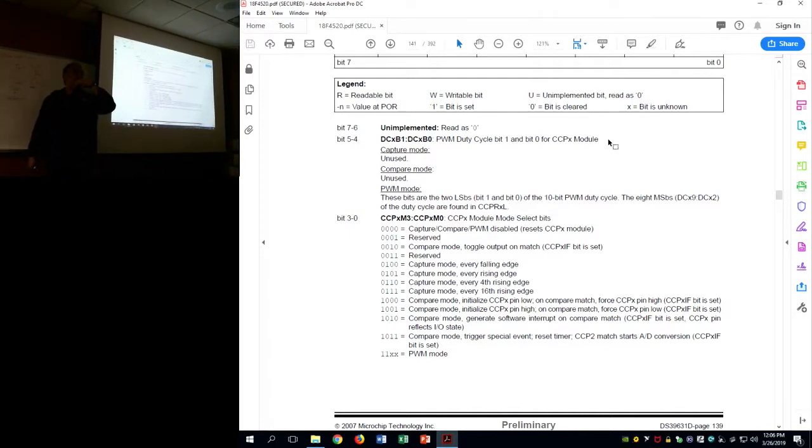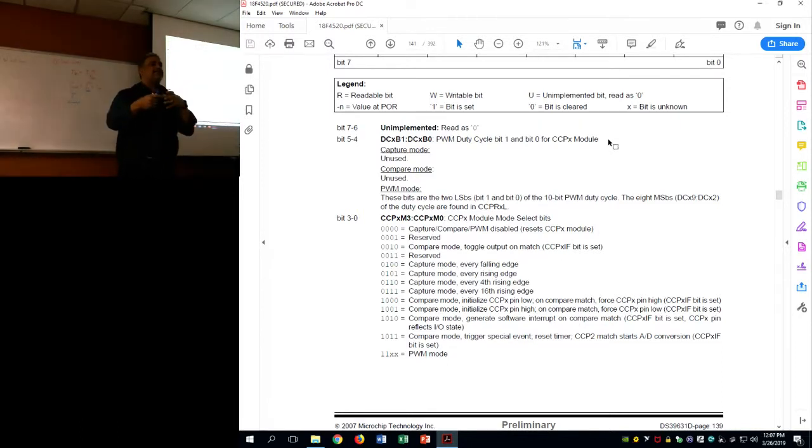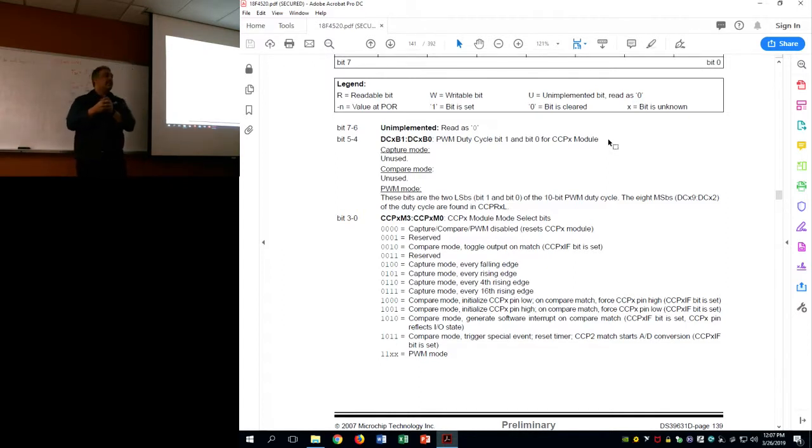Just to give you a little bit of an idea, we use compare mode a lot to generate signals that look like PWM, but have variable power. So instead of having power equal to 5 volts, if you want to vary your power from 0 to 5, 0 to 3, and then change the frequencies and the duty cycle, these compare modes are what we tend to use. We created a pretty cool application where we take medicine that goes into a chamber, and then we create plasma inside of the chamber to change the chemical composition of that gas, and then deliver that gas to the lungs of children in the intensive care unit. We were using 4 of these timers operating together to create variable amplitude and variable frequency across a specific amount of time. So this is a very useful skill to have, understanding how these little guys work. And they're very easy. We'll show you in a little bit the application and how this works.